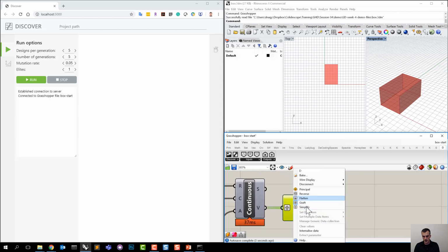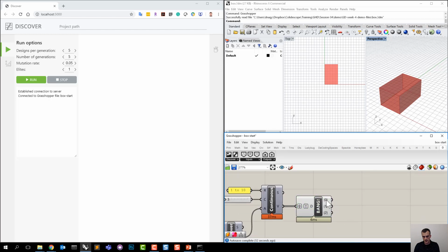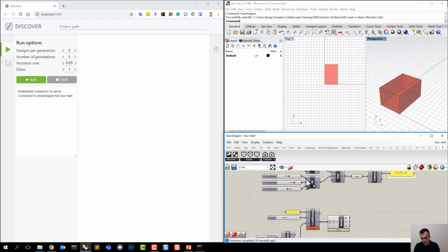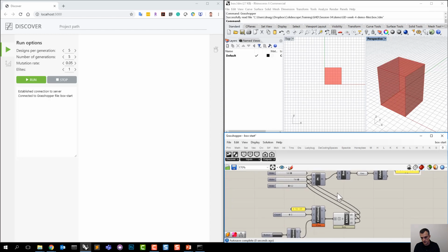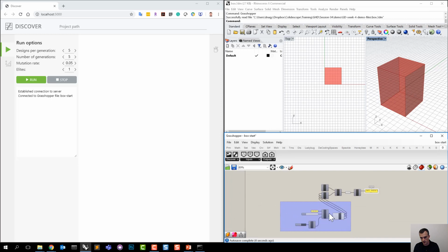We can also simplify it if we want something cleaner. And then to match up the number of branches we have in our tree to the number of outputs here, we can right click on the component and say match outputs, and it'll basically create a separate output port for each of our parameters. And now we just swap those for our inputs. We can delete our sliders now.